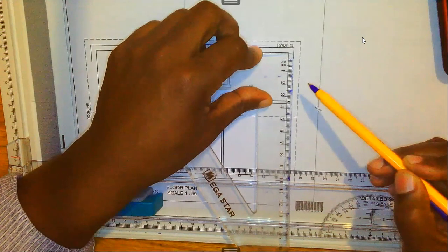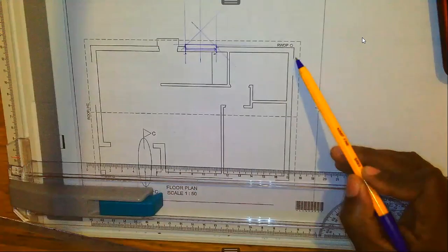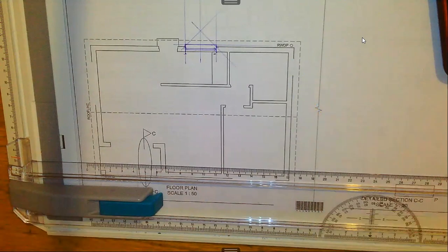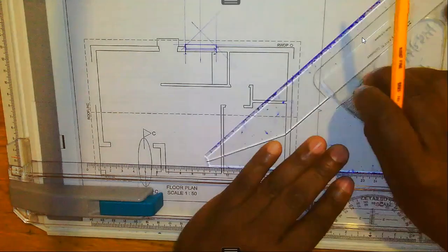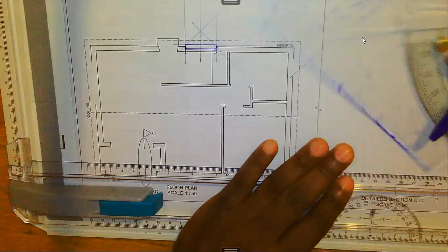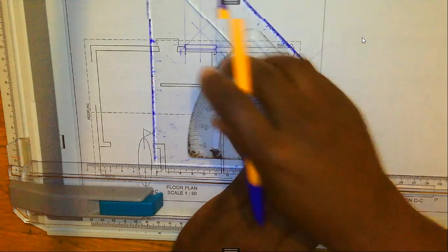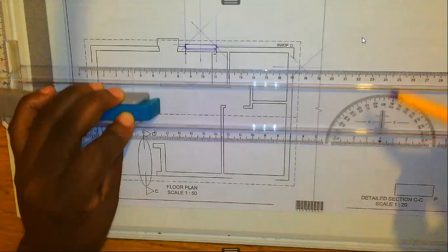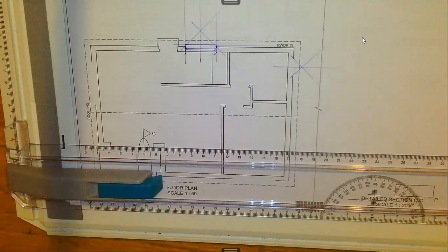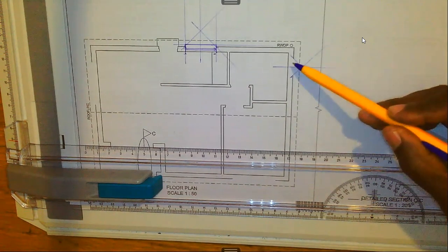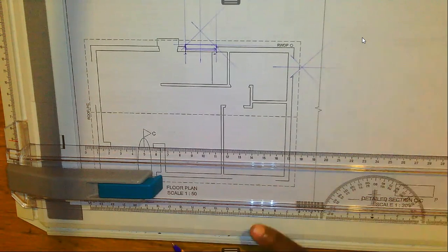So what we need to do is to find the midpoint. Boys and girls, you don't need to struggle with regards to this. Just take your 45 degrees set square at the end at 45 degrees and at the end at 45 degrees like that. You will get the midpoint. Remember, our subject is engineering graphics. Our answers should be presented solely, if possible, in form of graphics, okay? You don't want to waste the time dividing, multiplying, this and that. That's not necessary. Get the answer graphically, okay?